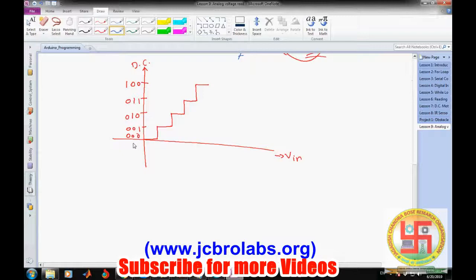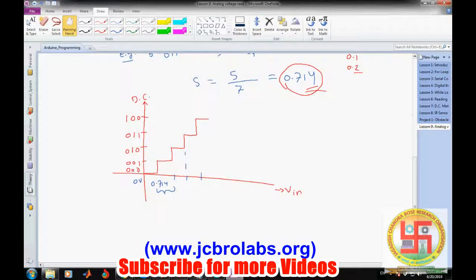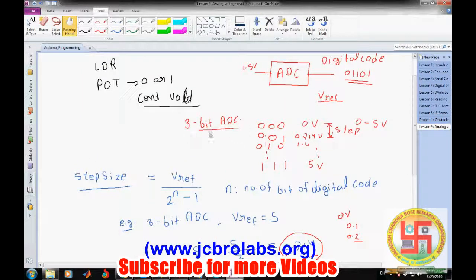So the input voltage could be, this is 0 volt, then it will be 0.714, which we just described, it is 0.714 plus something, and then this one. So this much voltage has been lost in the ADC conversion. So it is obvious this particular step size is directly dependent on this n, the number of bits we are going to use. Suppose this number of bits goes higher, so this step size keeps coming down, and we can get a better resolution in the digital code, right?